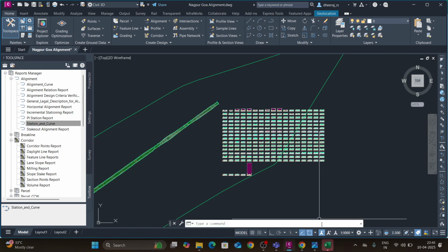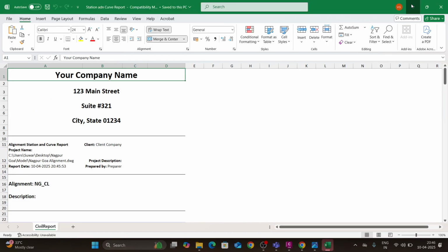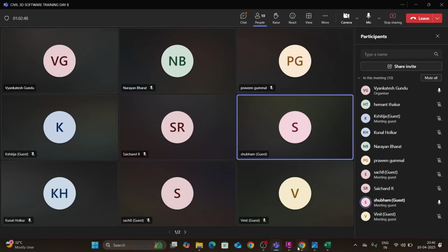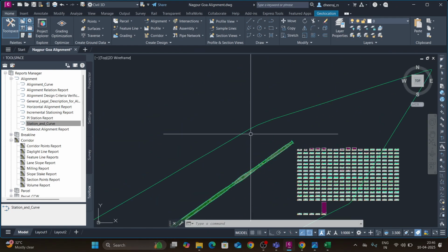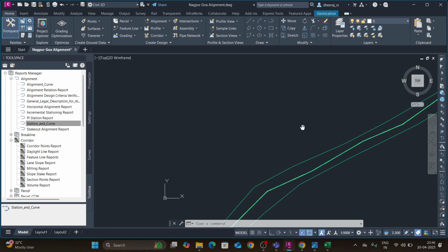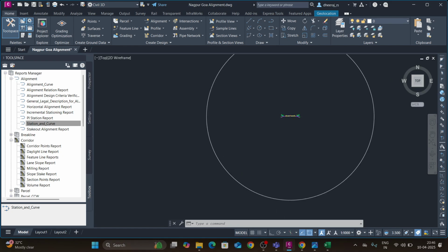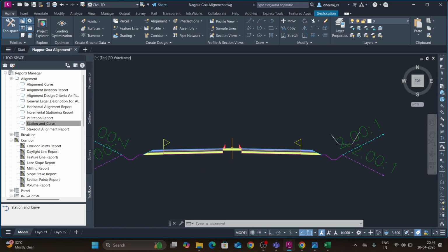Sir, in last lecture you have taken that crash barrier one. In some highways they use MBCB; do we have to create it, or will it come? No, no. For MBCB, you have to directly take the quantities. It is on a length basis. Then how much length will be provided for the MBCB, that much you can calculate.